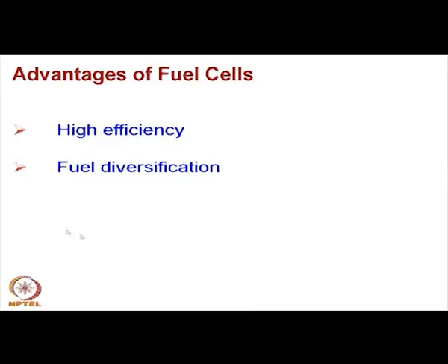So, one can have different kinds of fuels, but the most important characteristic is its high efficiency. Zero emission and silent, compared to many other mechanical systems like generators, gas generators and so on, or steam generators, you don't have a moving part here. It's basically a stationary system, except for gas supply and air supply. You need some blowers and so on, but otherwise the basic system is stationary. You do not have a moving part.